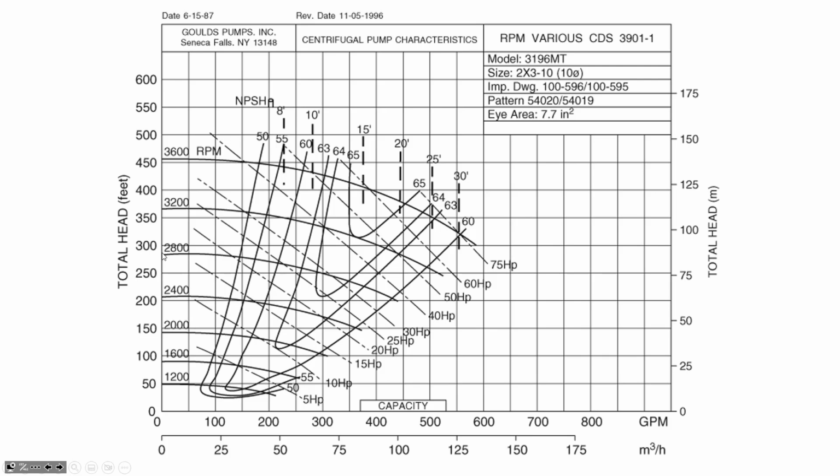Whereas if you put it together with a larger motor, which is rotating faster, at 3,200 RPM, the same pump, where we're not changing any of the internal characteristics, we're just driving the shaft faster, is now going to generate about 365 feet of head instead. So rotational rate is one of the factors that affects the pump performance.